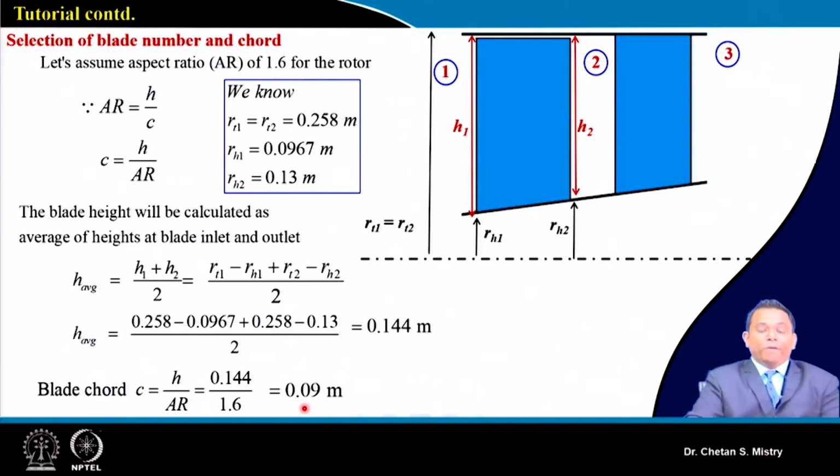Now many times when you go with this assumption, this number may come slightly on the lower side. And realize one thing, when we were discussing the contra-rotating fan design, we realized that part. My chord will be coming very small. When the chord is small, you need to do a whole lot of diffusion with a small chord.